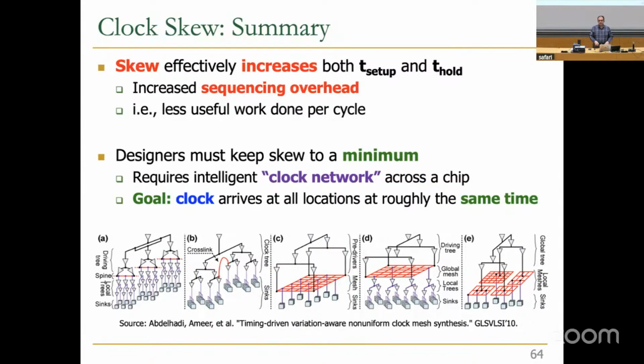Because if you look at the clock network, you usually have different layers in your chips to route clock wires. And when you want to do some computation on your clock, to change your clock, you basically need to bring that clock wire to your logic. And that causes some delay, actually.